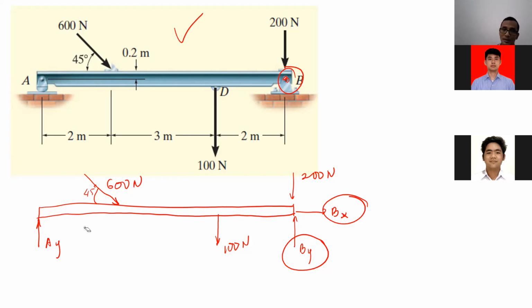But remember, a free body diagram does not necessarily have to be completed only with the forces, you have to complete it with the dimensions as well. So in order to draw the correct free body diagram, you have to draw the dimensions. Basically, a free body diagram is a tool to help you solve the problem.